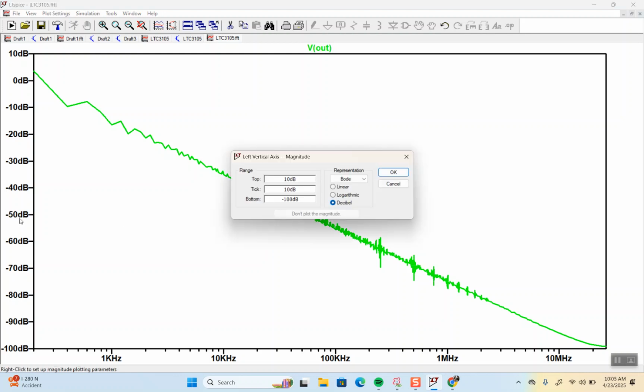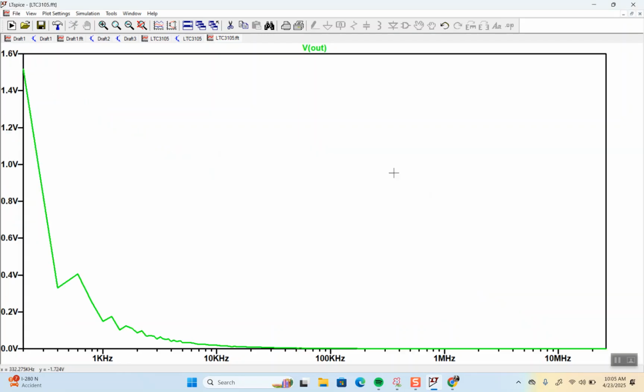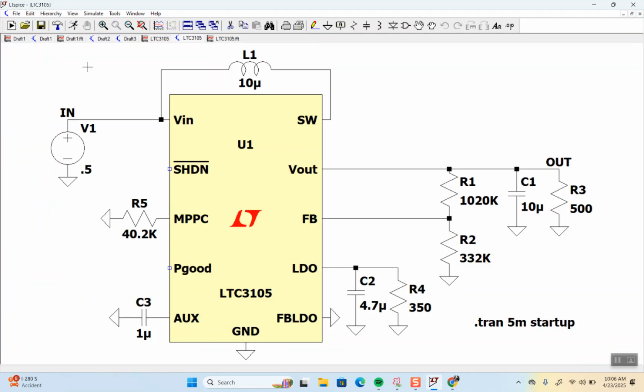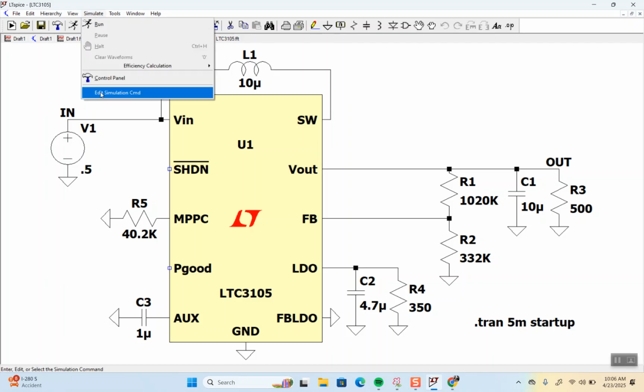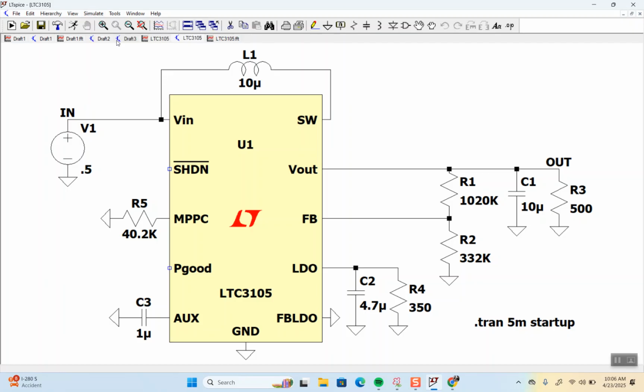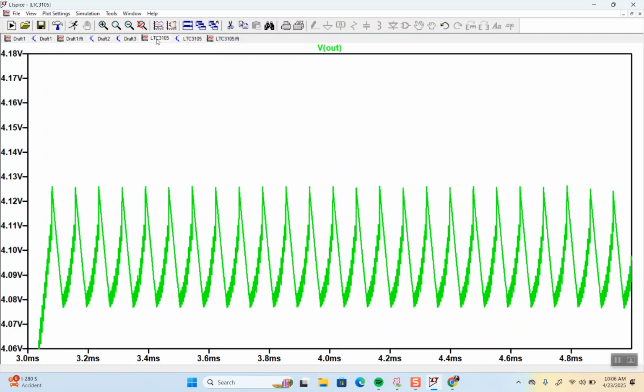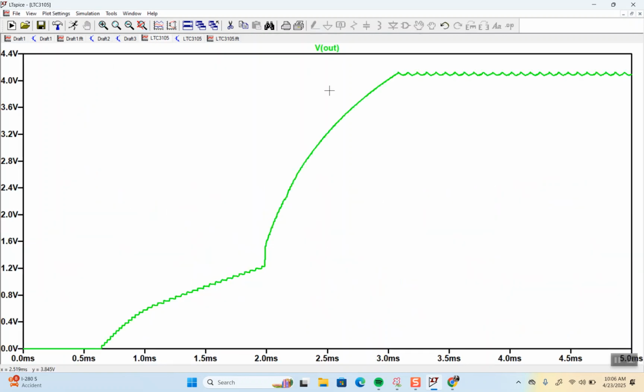So yeah, by the way, LTspice gets rid of the DC part, but I've got a component at, I don't know, less than a kilohertz. I don't like the analysis. So I'm going to run the simulation longer, but save it so that the initial 3 milliseconds isn't going to show.